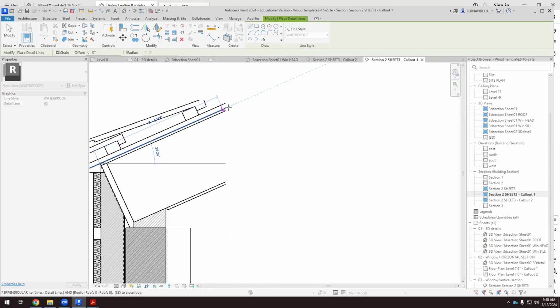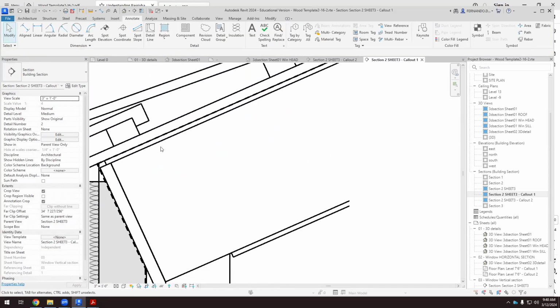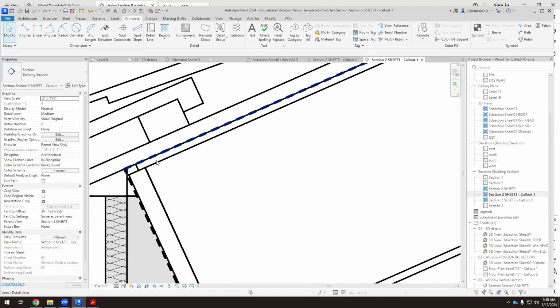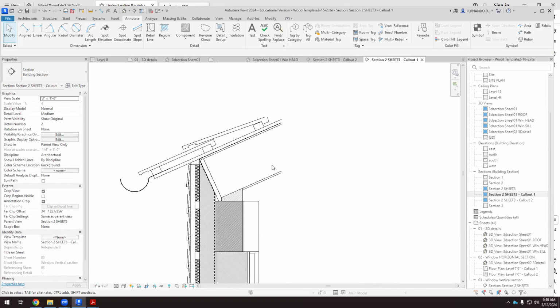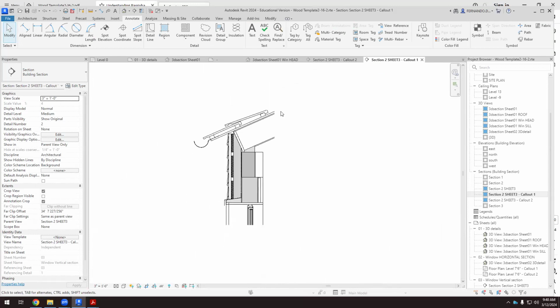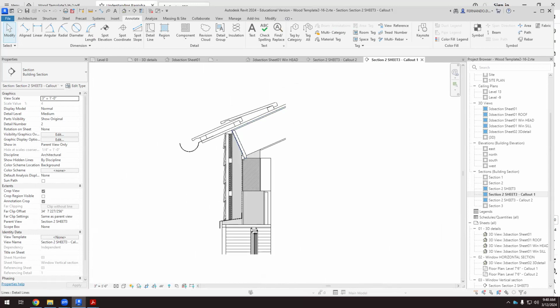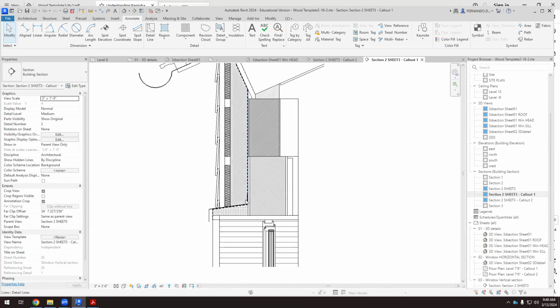And then on the roof, it will be like this. Okay, so now we have a continuous barrier, and when we interrupt this, because we open the window, all the water that can be stopped here has to go down, and then it has to go out of the building.